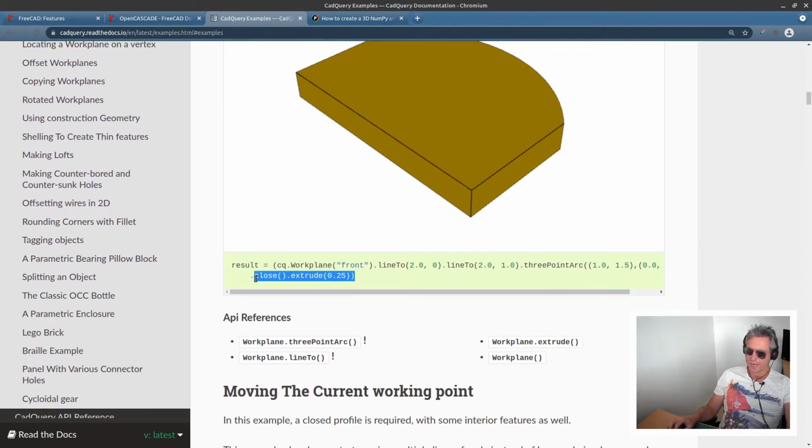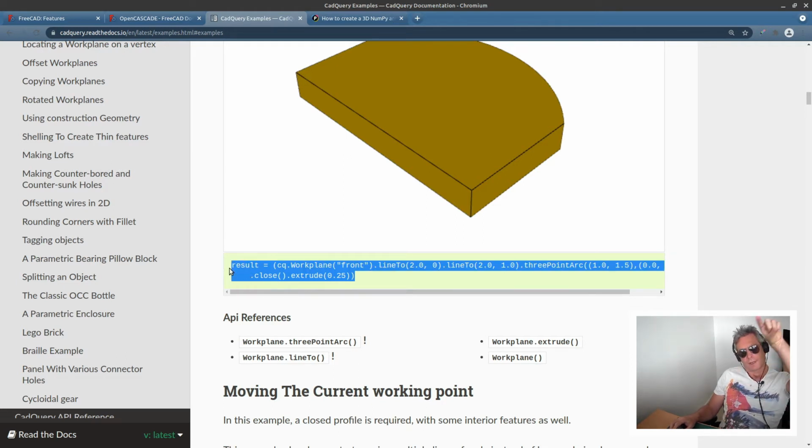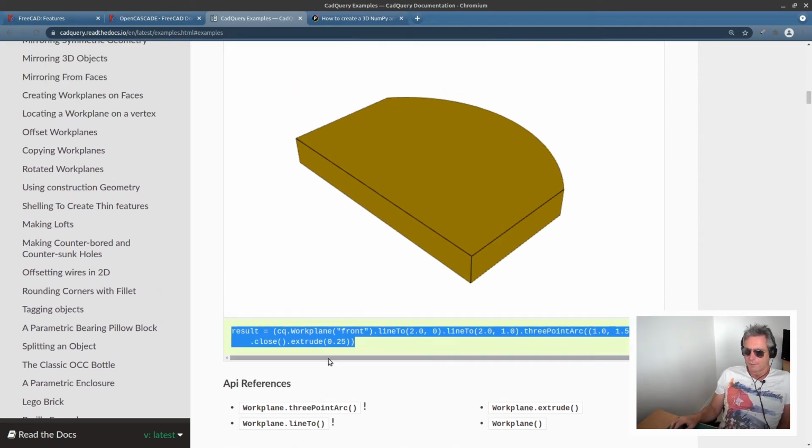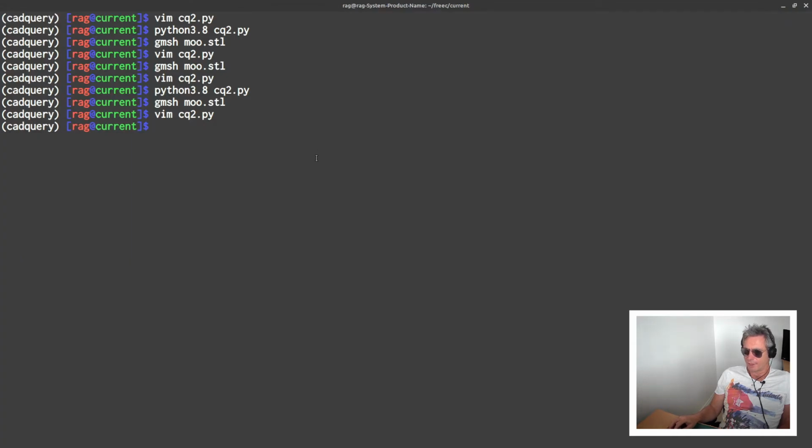So if you've used CAD before, you'll know that with polylines, if you're drawing a rectangle, you draw 1, 2, 3, and then you type CL for close, and then it closes the rectangle. So with CAD, you always need to close a 2D shape before you can extrude it.